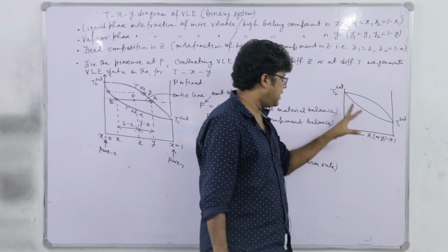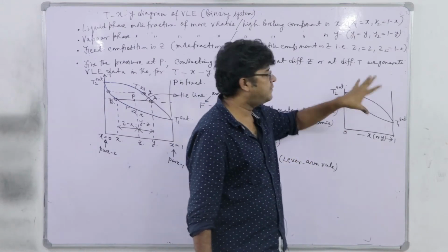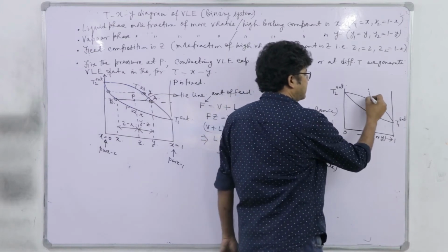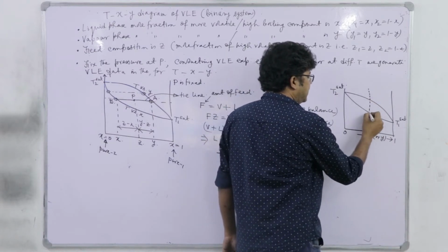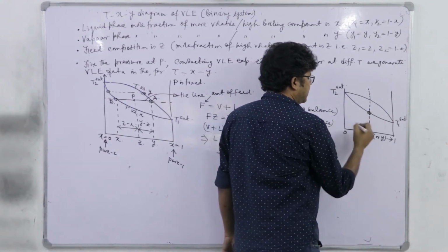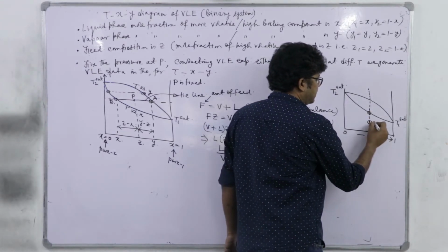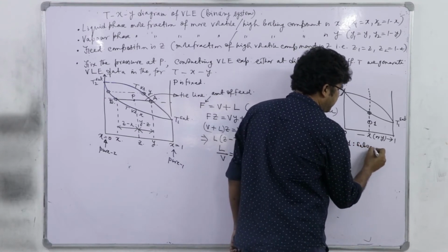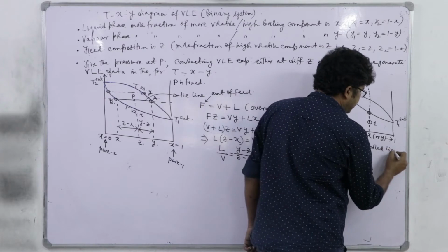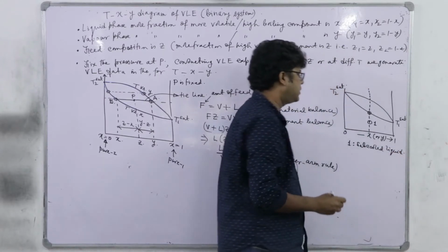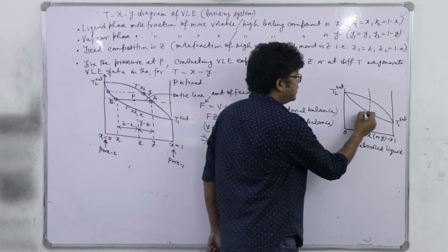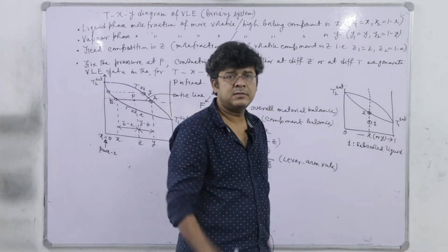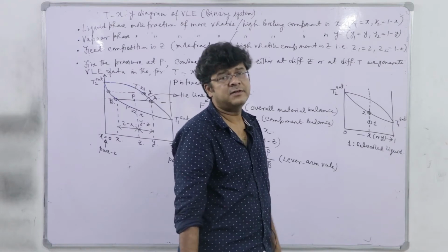So, additionally, there are 5 different thermal phases possible. So, for a given Z, when we are here, this is state 1. So, state 1 stands for subcooled liquid, right. State 2, when the first drop or first bubble of vapor appears.